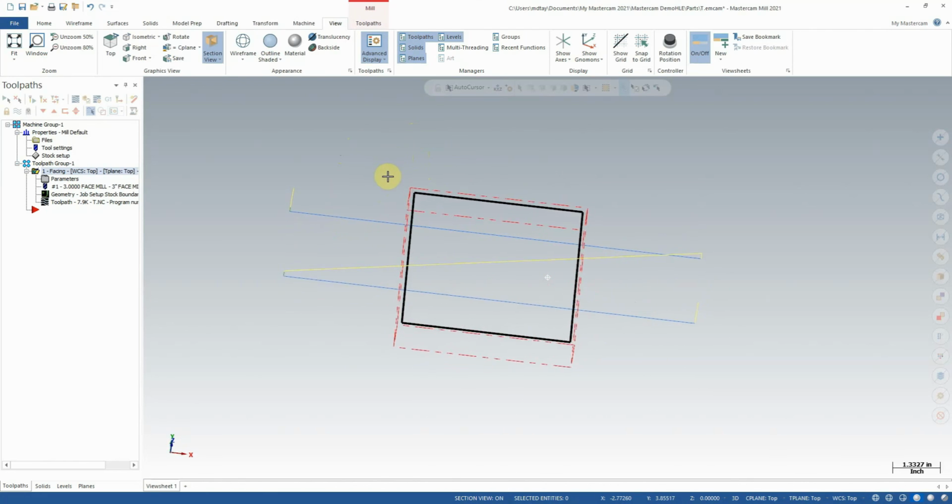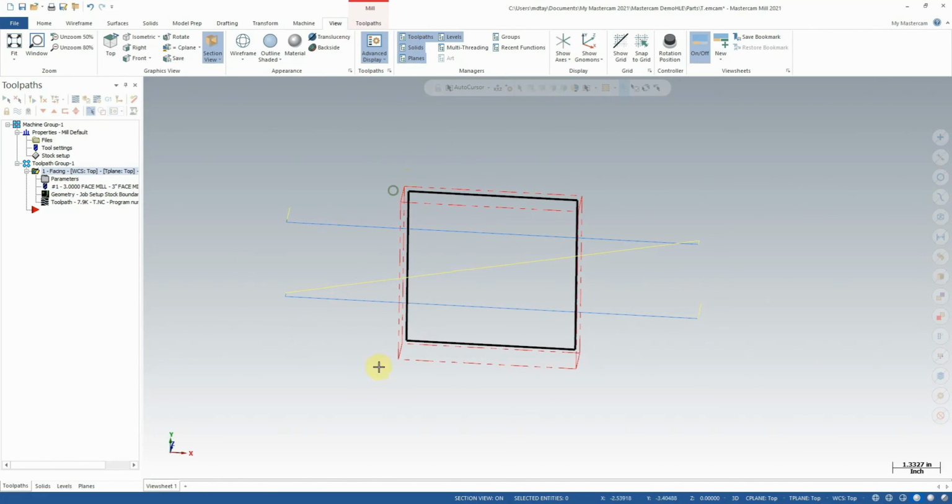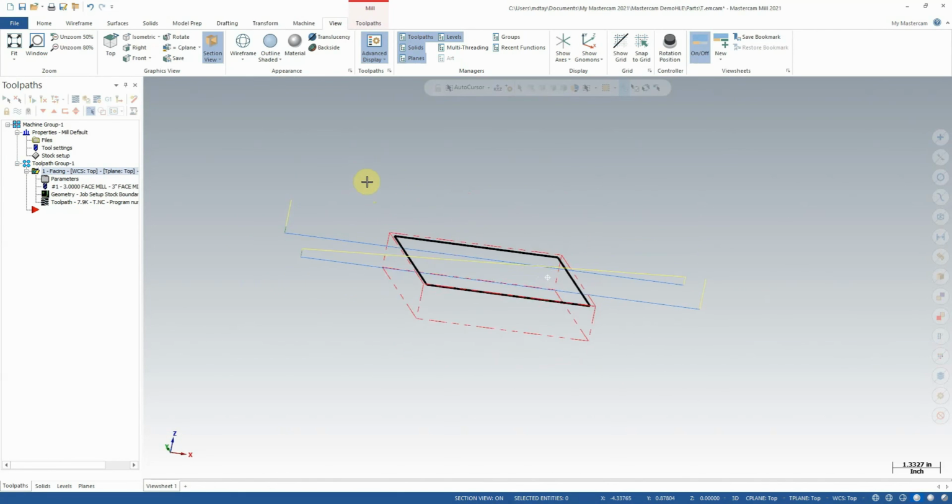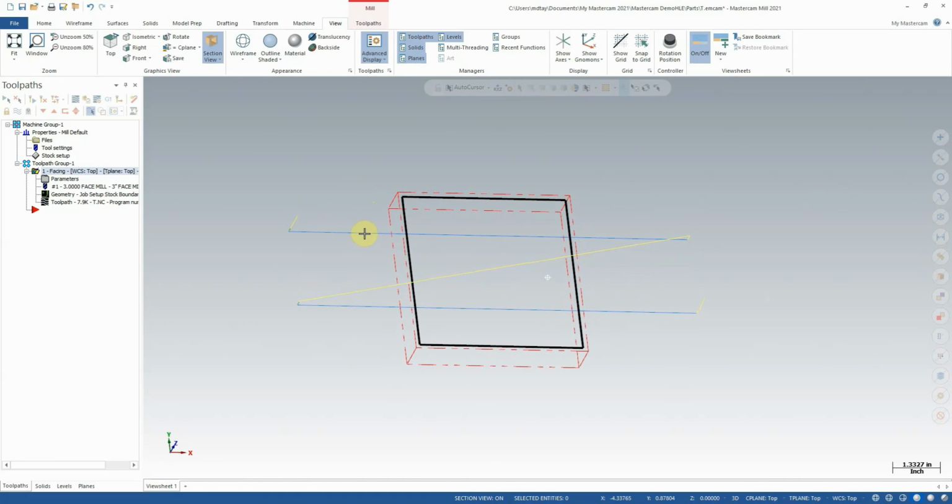So in this case, we've potentially saved 50% of our cut time on this toolpath just by reducing the number of cuts by 1. Again, in a project like this where we're not physically machining this part, that may not be a huge deal, but if we were actually manufacturing this, perhaps even thousands of these, you imagine you've cut down 50% of your time on just one of the toolpaths. That could result in multiple hours, tens of hours, hundreds of hours of saved time down the road. So even little tweaks like this are worth it.